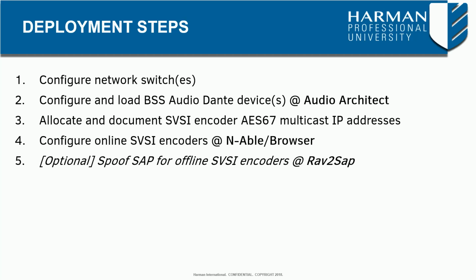We can manually add in SDP packets for devices that do not exist, which will allow them to show up in Dante Controller. This then allows us to pre-configure the Dante interface without having the AES67 sources. Of course, for the next item, we'll want to configure Dante devices through Dante Controller.